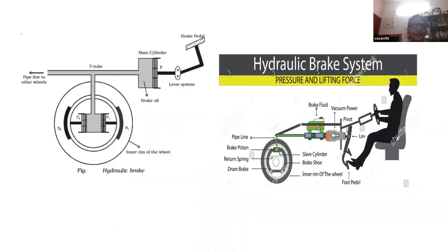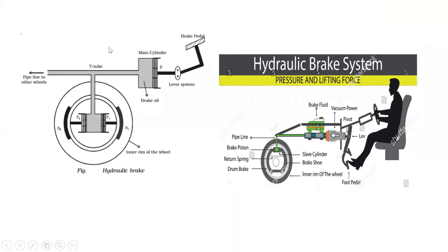Now, hydraulic brake system. It is also based on Pascal's law. When I teach that, I ask the students to observe the driver. The driver of a bus or car, your parents, how many pedals are there? There is a brake pedal, an accelerator, and a clutch. So what happens when the brake pedal is pressed? There is a master cylinder, and the liquid in the master cylinder is pushed into the wheel cylinder.